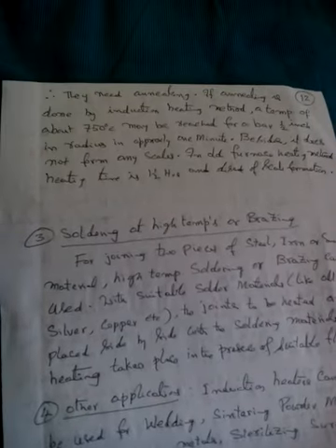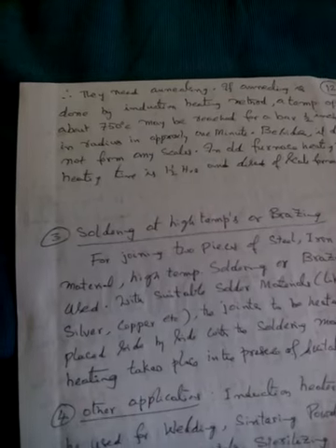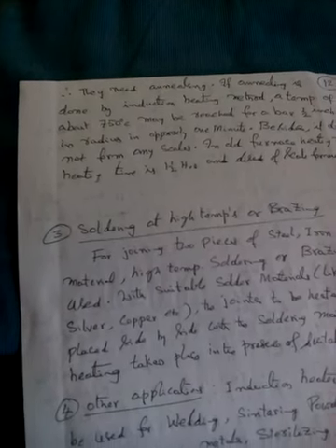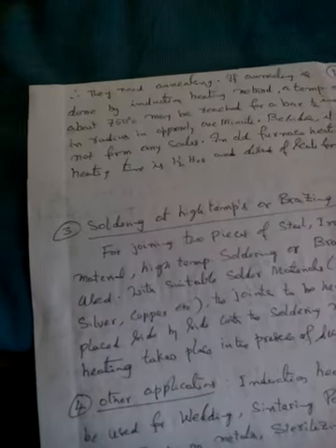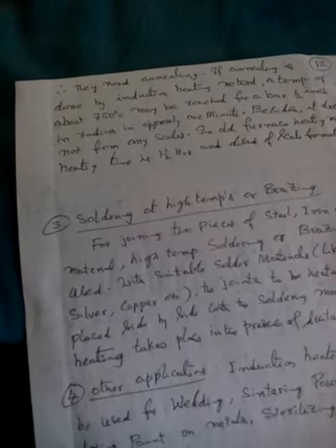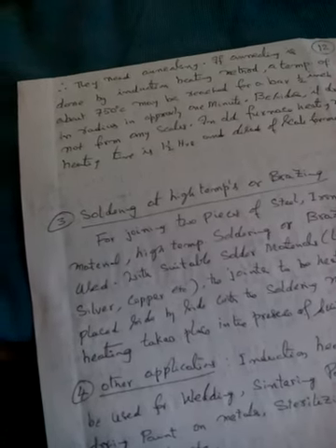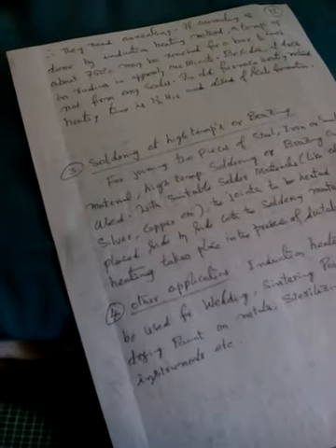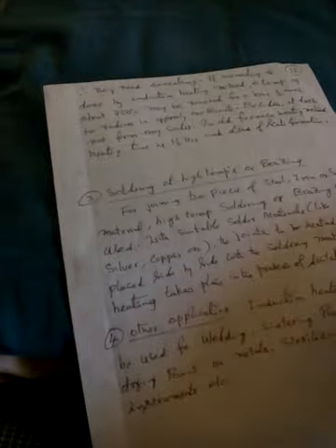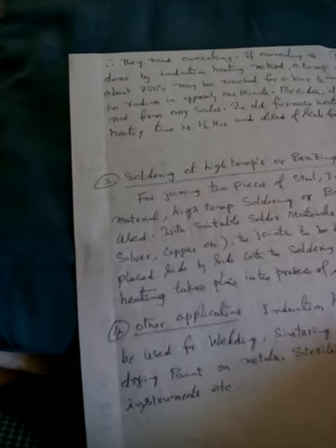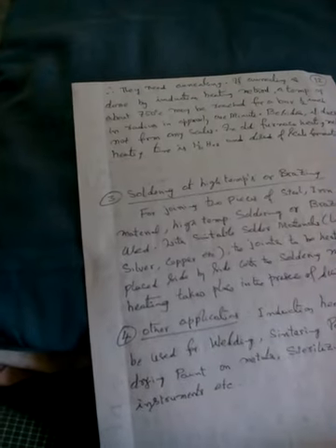a temperature of about 750 degrees centigrade may be reached for a bar half-inch in radius in approximately 1 minute. But of course, you want to reach this temperature, normal old furnace method will require 1.5 hours. And also, we get what you call a scale formation.